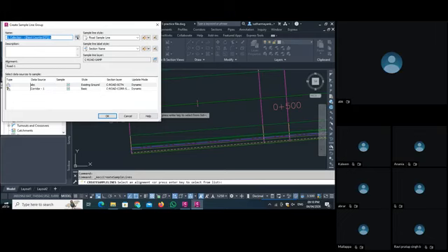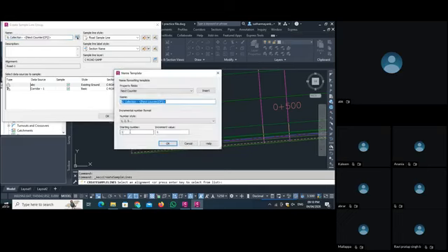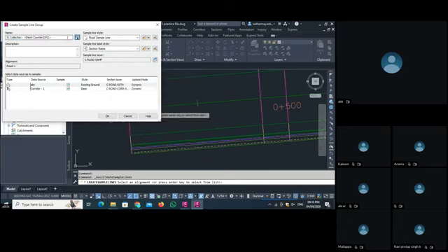You can set the name here, SL means sample line, and see the starting number is 1, so not an issue. So it will create SL collection 1. Now the sample line style is there, label style is there. So all those things, that's why I took a long time in points and surface. Once you understand all these things, you can do it for any points.